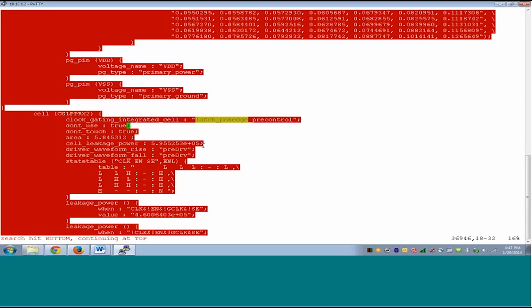This is a very special kind of cell. The functionality does not come from the RTL. This is an extra thing that DC adds to save power. Although the functionality remains the same, this circuit is extra and is not present in the RTL. It is only present in the netlist if we choose to add it. And DC should not use this cell to infer any other type of logic.